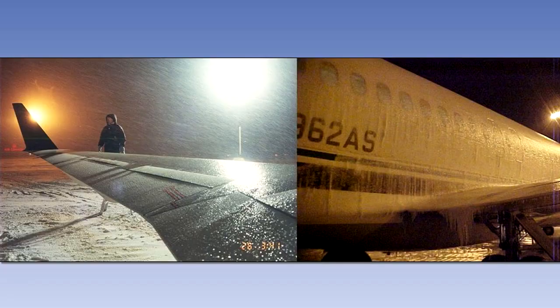The next factor that can affect the takeoff performance is contamination of the airframe. This includes the effect of airframe ice and excess water. Airframe ice will accumulate as a result of icing conditions being present at the aerodrome. These conditions could have resulted from a frost, freezing precipitation, or from snowfall. The effect of these contaminants can be significant if they are not properly removed.